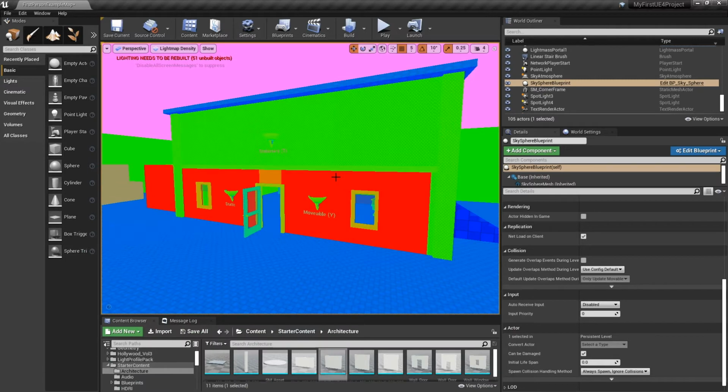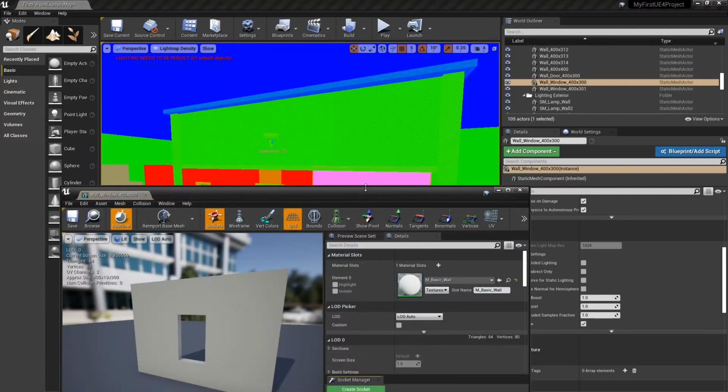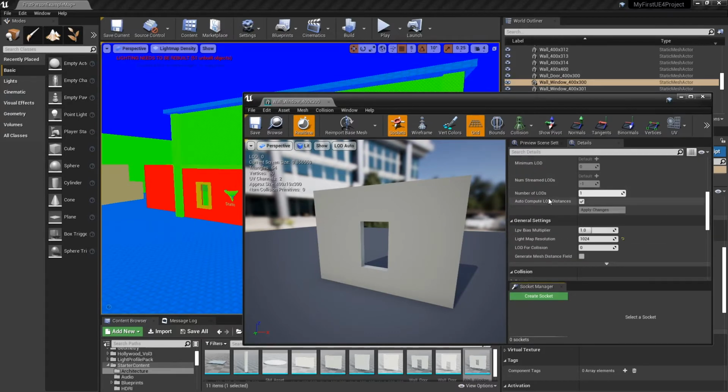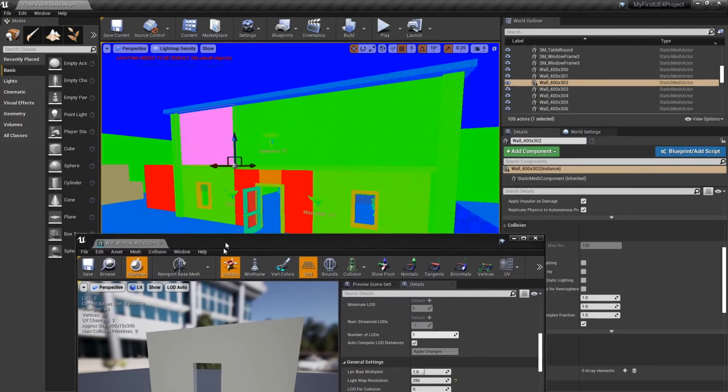Great. So now let's select these. And what I have here is I've set this to too large of a number. So let's Control B, go in, and we'll try a couple different resolutions and see what will fit in terms of making this green. So we'll scroll down to General. Let's try half, so 512. And we're getting there. It's lighter. Let's half that, 256. Hey, there we go. That's looking nice and green.